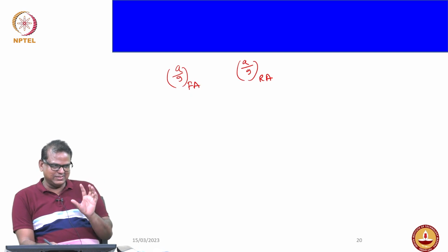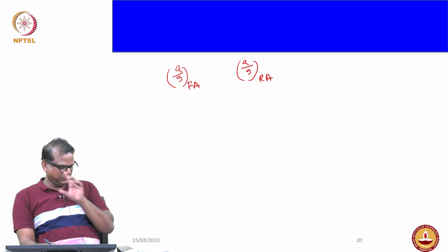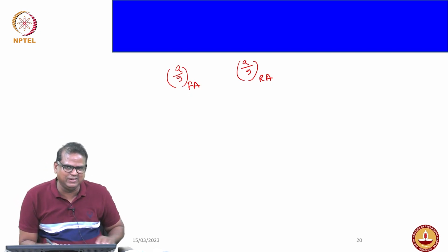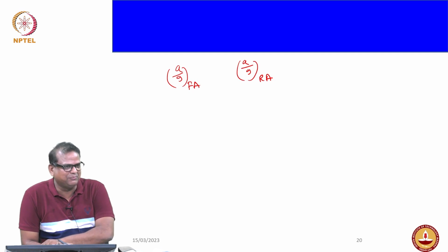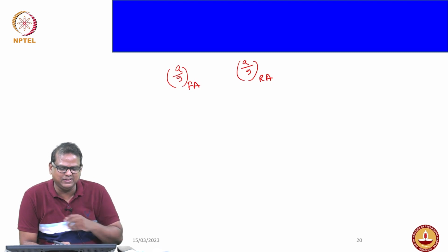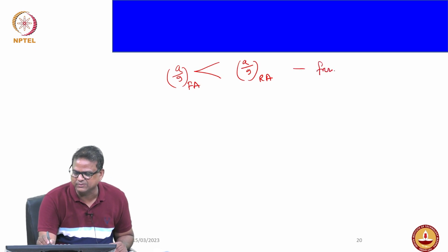We are not discussing any negative aspect. We are taking the quantity as it is without any sign, because when we do the problem there will be confusion. So before that I am just giving a clarification. Let me ask, when do you expect the front will lock first? When the deceleration rate of the front axle is less than the rear axle, the front will lock first.